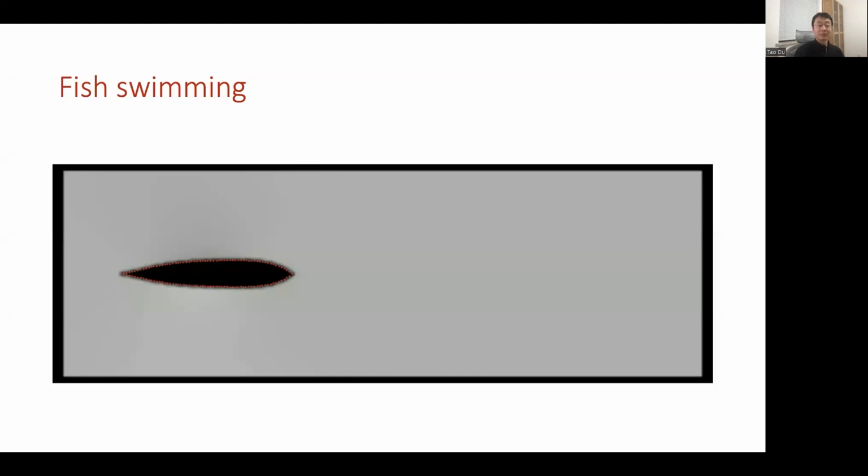The first challenge is obviously that we have to deal with fluidic mechanics, fluidic dynamics. And similarly, just like any other solid fluid coupling problem, we also need to deal with solid dynamics. But since our problem is to simulate a soft robot, a soft fish, the solid dynamics is also slightly more sophisticated. It has to be a deformable solid. And the third challenge is, of course, you have to do coupling between solid and fluid areas along the interface.